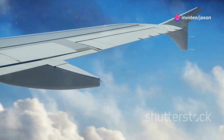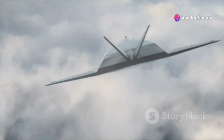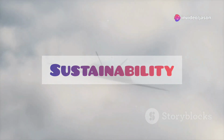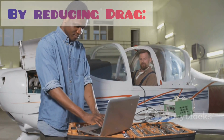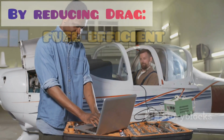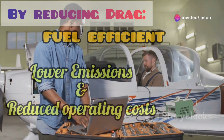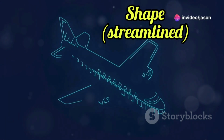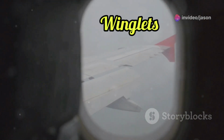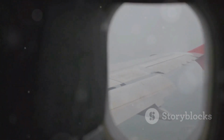Efficiency in the air, saving fuel with aerodynamics. In a world increasingly focused on sustainability, aerodynamics is more important than ever. By reducing drag, engineers can make aircraft more fuel efficient, leading to lower emissions and reduced operating costs. One way to improve fuel efficiency is by optimizing the shape of the aircraft. For example, winglets. Those small upward-pointing extensions on the tips of wings help reduce drag by altering the airflow around the wing.